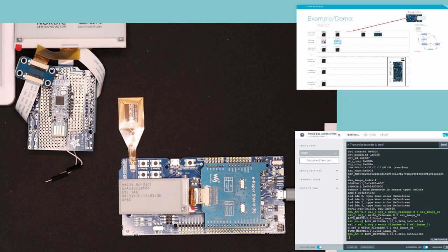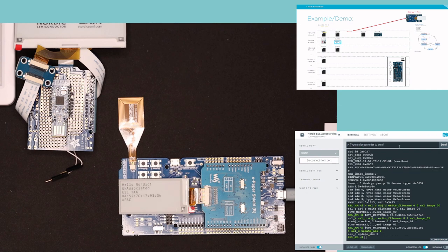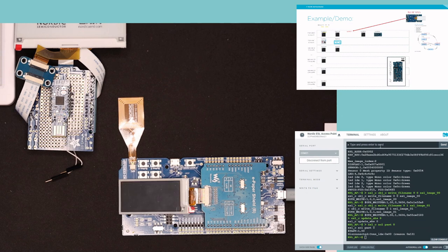We can also transfer the absolute time from the access point to the tag, so the tag has the same time as the access point. Once this is completed, we can use the PAwR procedure to let the tag synchronize to the access point. The tag disconnected, and you can see that now the tag has changed the screen. It says that this is now associated with the ESL address that we wanted, and the LED is blinking in a different way because now the tag is in a synchronized mode, and the LED will blink only when the sync packet is received.